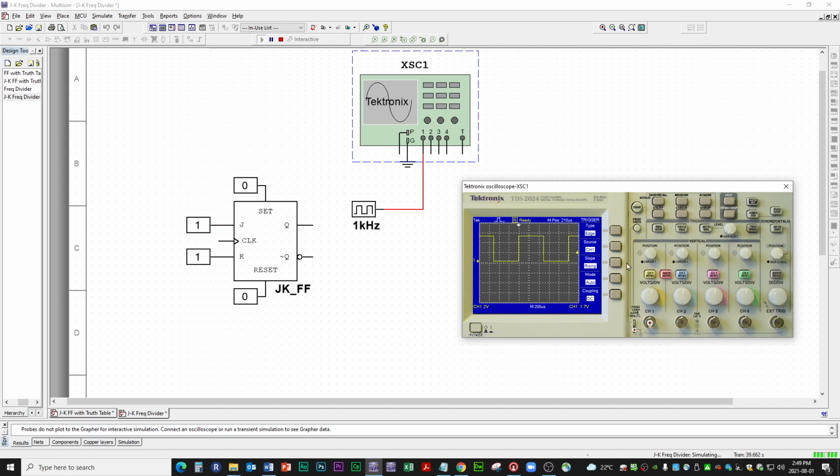Okay, let's do a measurement. All right, call up the measure facilities on this scope, and the menu shows up. We are measuring channel 1. Good. Channel 1 source, channel 1. Okay, type, what do we want to measure? Once we choose the quantity we want to measure, we're going to have these little guys light up, which means that they're going to be our controls.